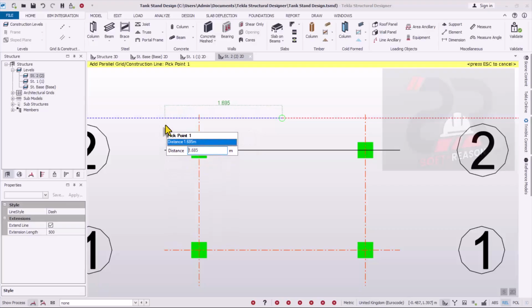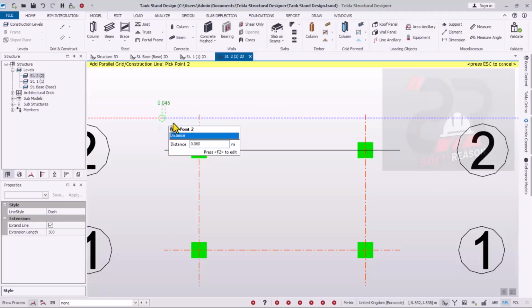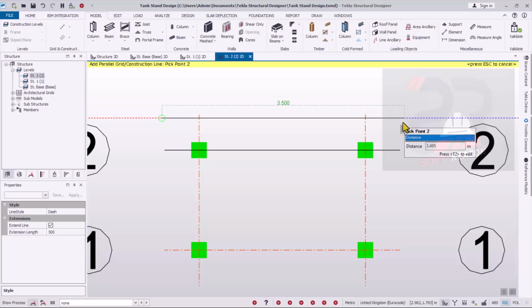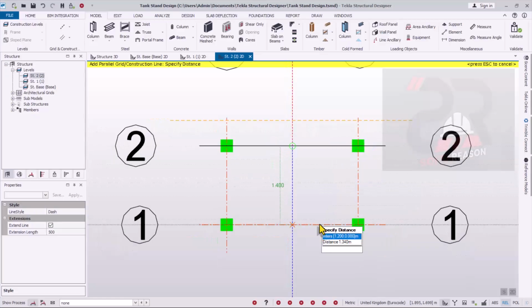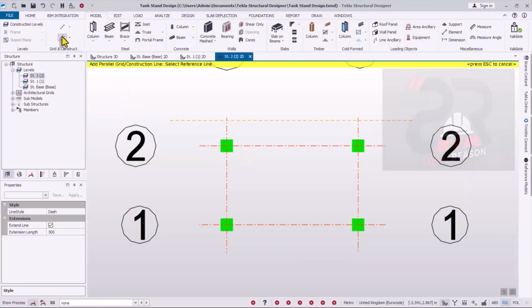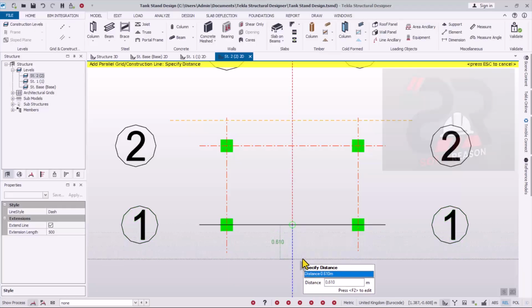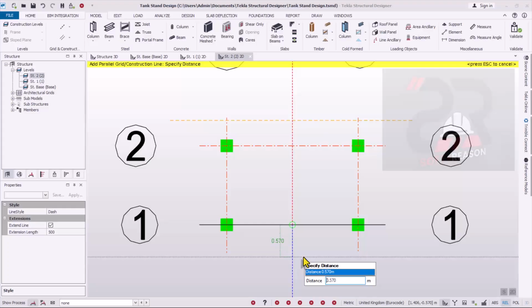All right, so that extent is being marked successfully. So you will now start to pick the first point, and then you pick the second point of the line, just like this, to have it placed. You can see. So you escape, and then you have to do the same thing. Pick on that parallel line, select on the green line, move it this way, press F2 on the keyboard again, and then key in. Sorry, you need to use the tab key this time around, just like this, you see.